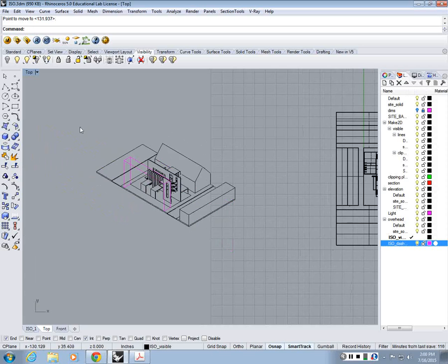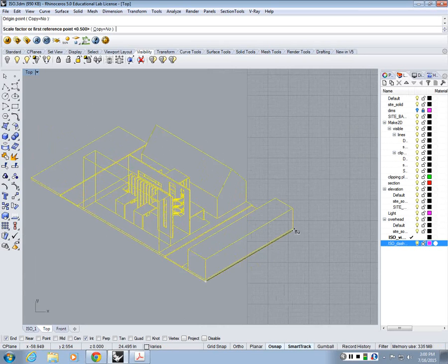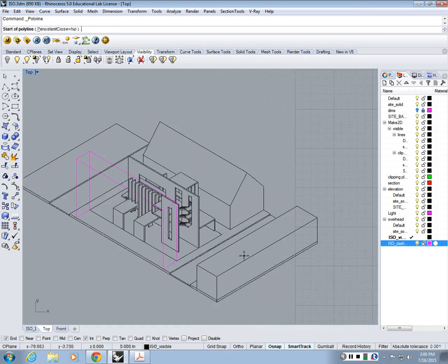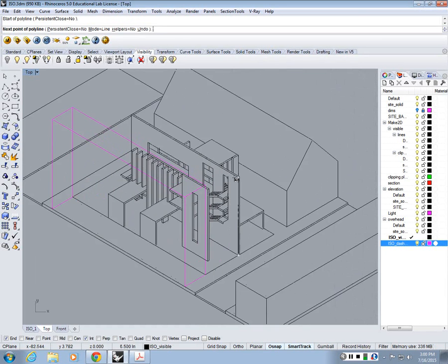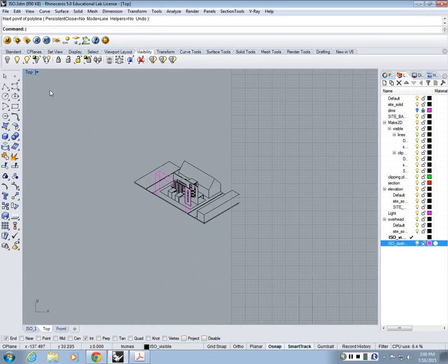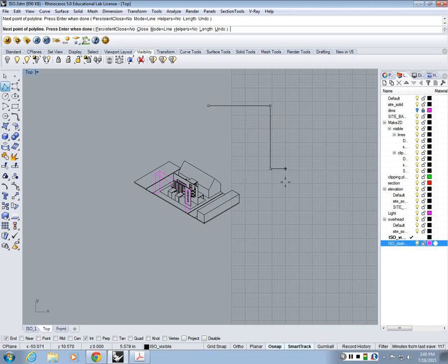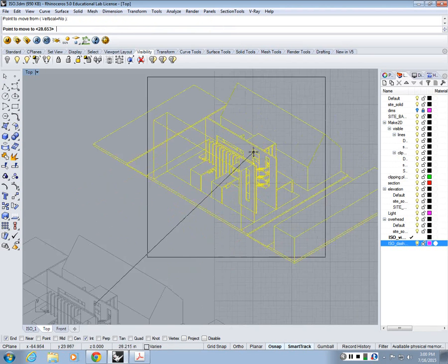Right? So then what I did was, I'm doing it in inches, but basically our model was drafted in 1/4 equals 1 foot. So this edge has to be 15 to be 1/8 inch equals 1 foot. So this edge has to be 15 and this edge has to be 30. And then my main wall has to be 6.5 by 10.5, so basically half of the dimensions we had. Then I'm placing this inside a 23 by 23 inch artboard, so that this drawing is kind of in scale.